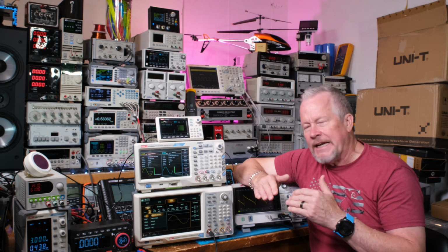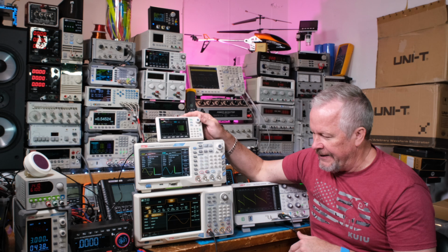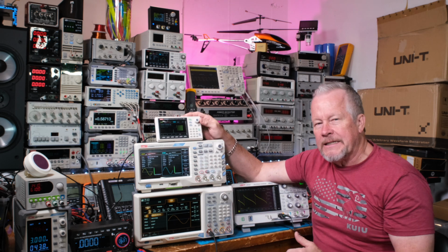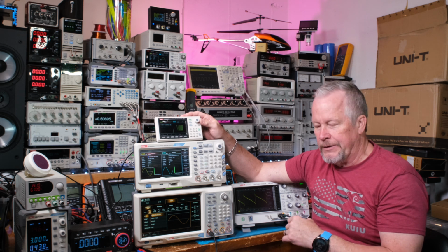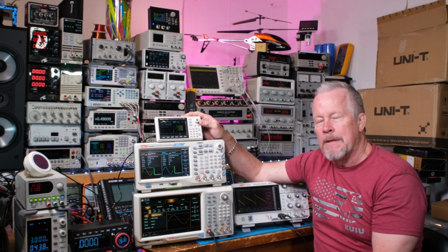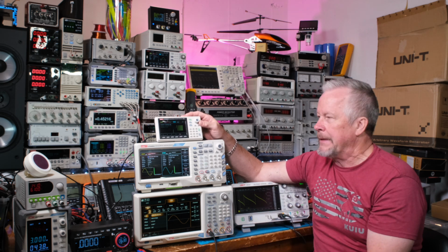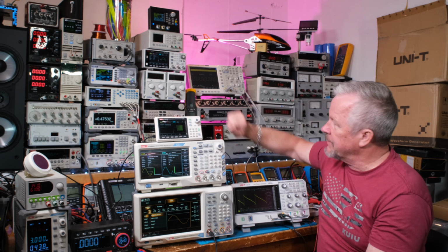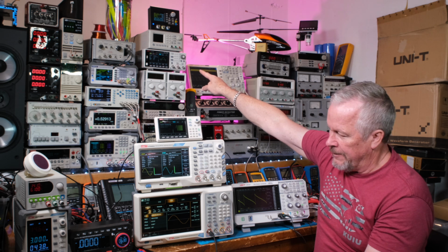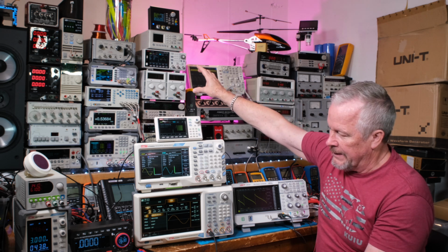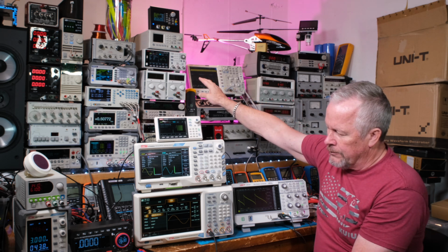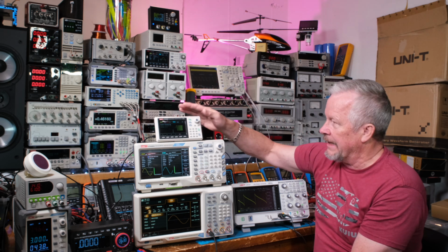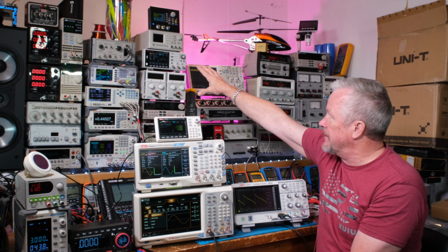Now, as the frequency changes, like on this guy right here, at 10 megahertz this guy can do that full voltage, but at 60 meg, that fastest frequency, it can only do 5, okay? So it drops in half, or 20 volts to 10 in high impedance. So that's this little guy. Just by comparison, the one up there, the next more expensive one, he can do the full 10 volts or 20 volts up to 20 meg. So like twice as fast as this guy. So that's another reason why he costs more than this.